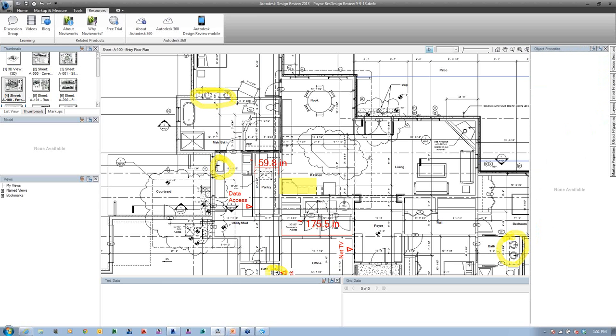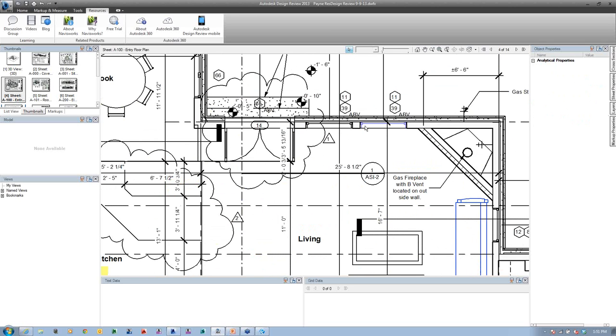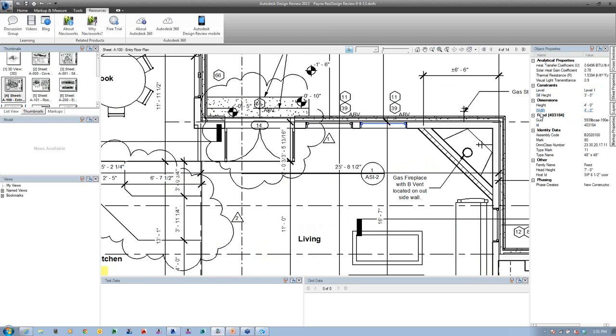And by looking at the properties, I can go in here and just pin this up, and what's nice about that is if I come over and let's say I select this couch, I'm going to get the properties of this particular sofa out here. If I go in and select the window, I can get the particular properties of that window. So whatever's been built into Revit, you can see the ID number automatically appears in here, the mark of that number, the type and the type mark are all in there. So we can start listing all these different things in here within Revit.